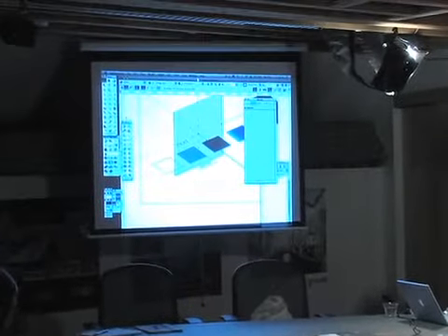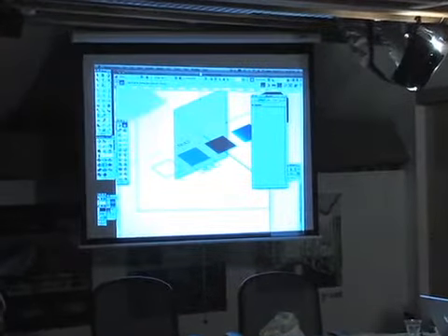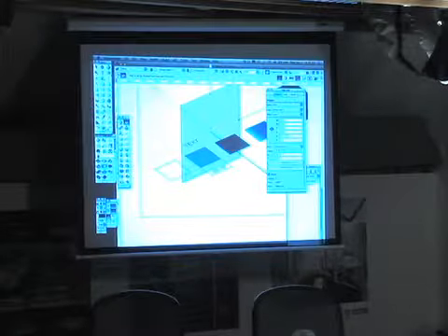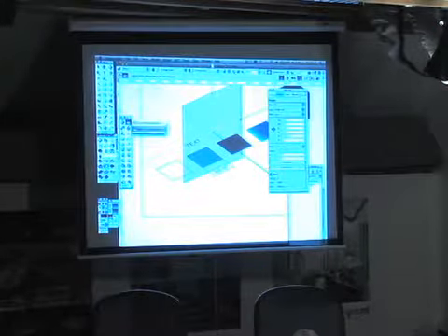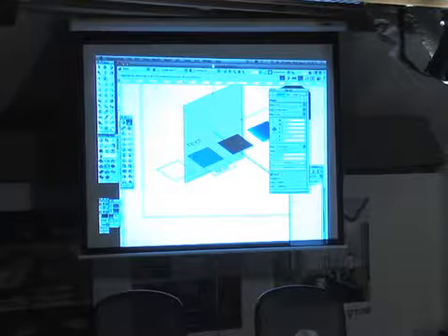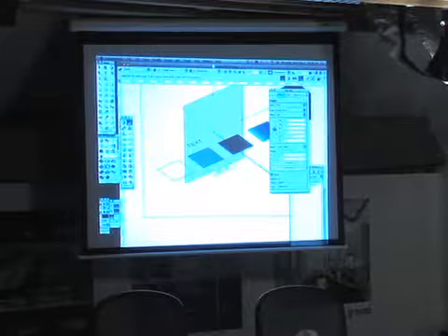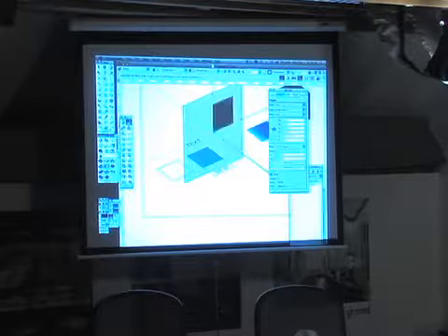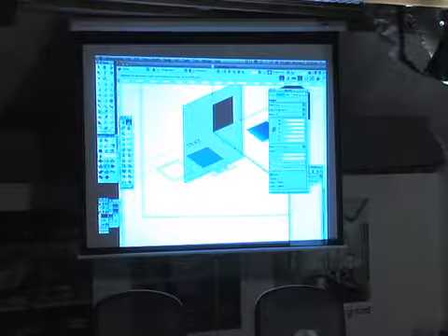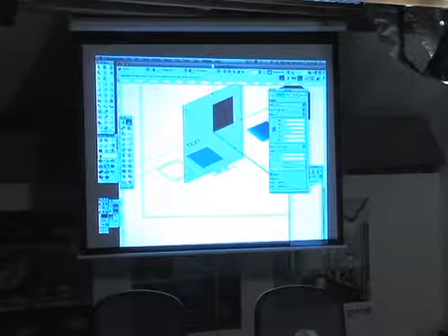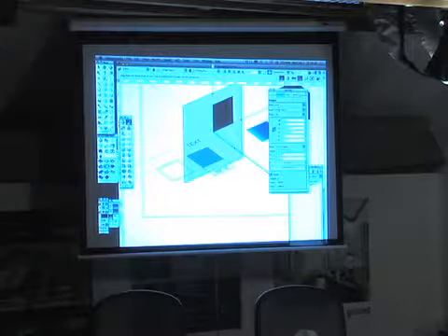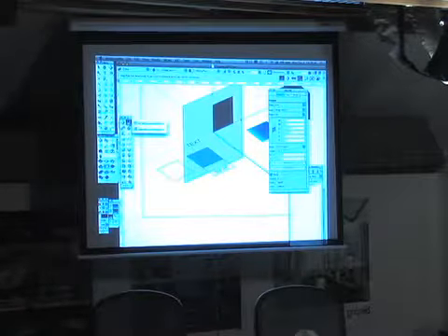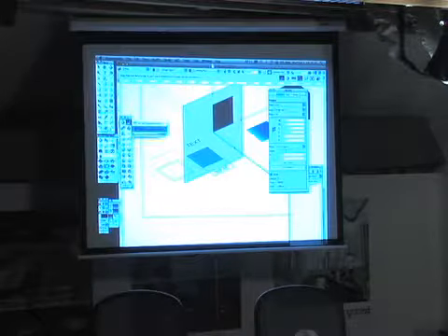And you're able to then reorient an object, flip it up in this other mode to shift it to the layer plane. I can click on this. Oops, I got to set my X and Y, and it automatically flips up to this new design layer, to my working plane. How to do that again? It's the hidden mode here under the set working plane. There's a line plane. Oh, okay.